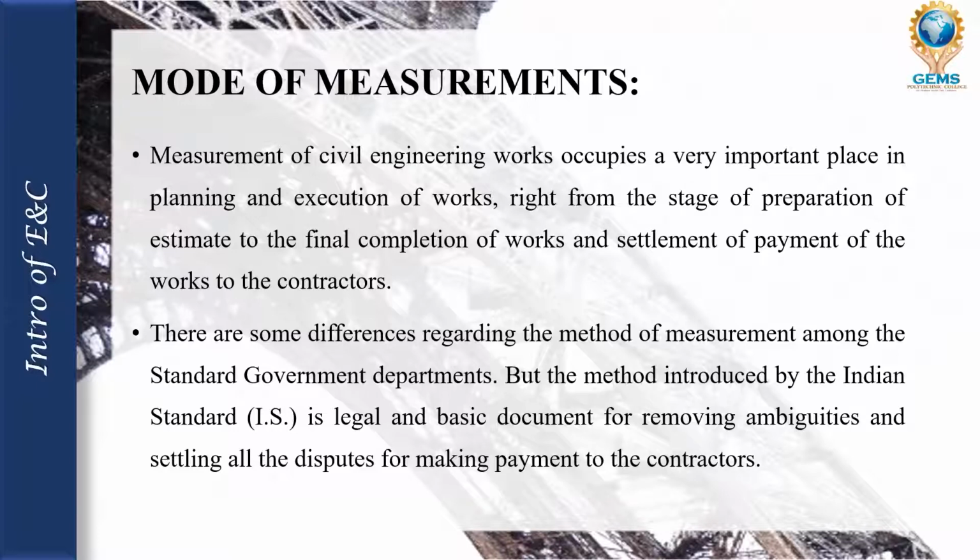Then the next topic we are going to study is what are the desired accuracy in taking measurement of various items of works, for earthwork, for lead and lift, for foundation trench, for puddling, for surface excavation, for timbering. Timbering means the planking and strutting required to uphold the face of excavated earth shall be classified under separate item and measured in square meter. Okay, so the unit of measurements we are going to study in this unit.